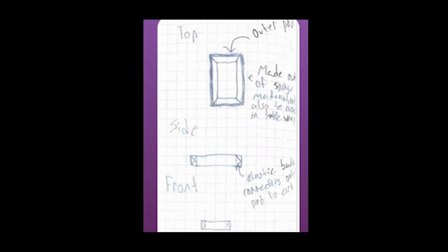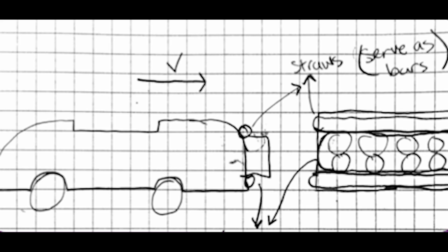Suspension pod. We also explored a suspension pod concept designed to isolate the phone and reduce vibration during impact. This concept improved sensor stability but introduced additional complexity and unwanted motion. Crumble cage. Another concept used a crumble zone style structure designed to progressively deform during impact. This concept distributed force effectively but sacrificed durability and repeatability after multiple tests.